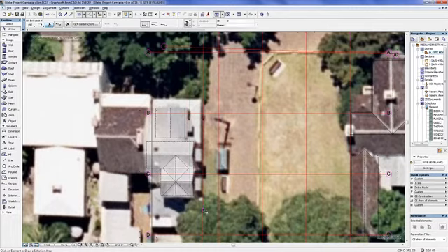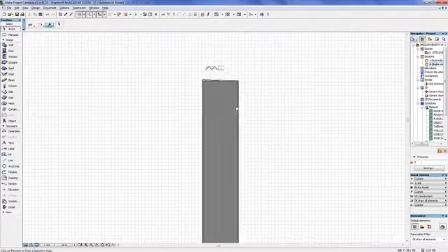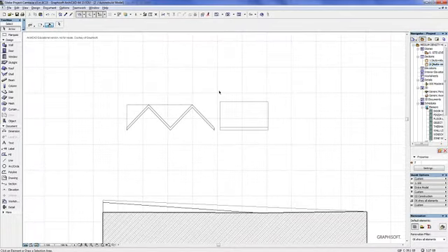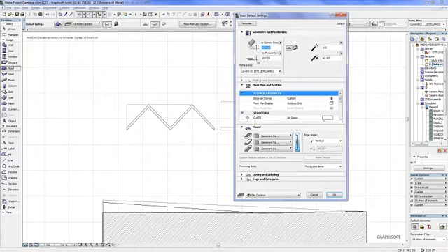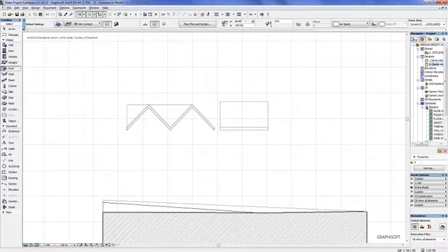Then I'm going to select the section, open the section. Okay, and here it is. Now, the first thing that I need to do is determine, well, what is the RL of this? Because it may well be already 109,560, but actually it's probably not, because the RL to the base of the roof plane is already 107,110. Okay, remember, the RL that is measured for roofs is to the bottom of the roof plane, just like this icon suggests, okay, to the bottom of roof planes.